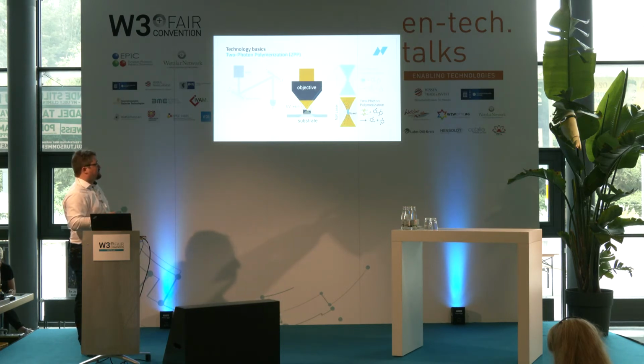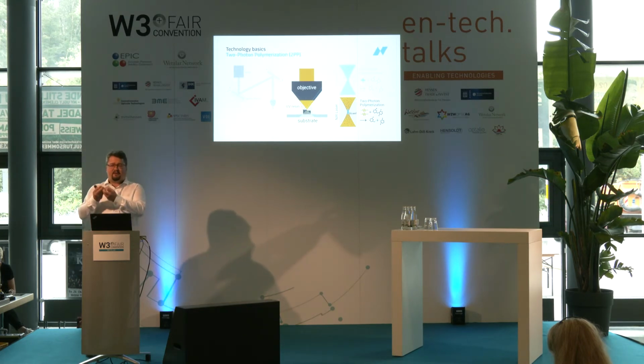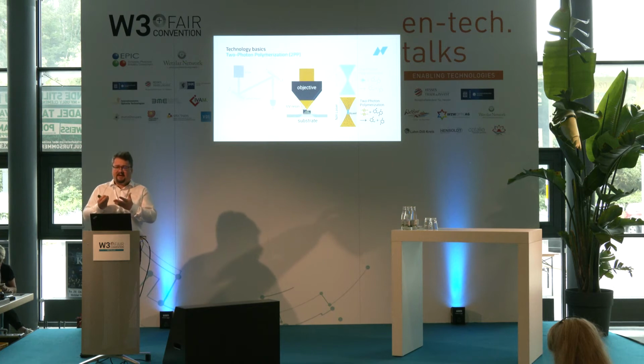We use a technology called two-photon polymerization, and that means that we take not a UV source, but a red or near-infrared source, so that the individual photons don't carry enough energy to do any interaction with the resin. Only if you have such a high intensity of the laser that you have two photons at the same time interacting with individual molecules, you get a reaction.